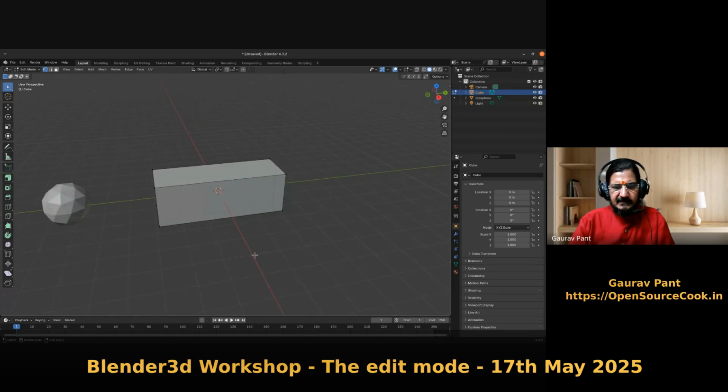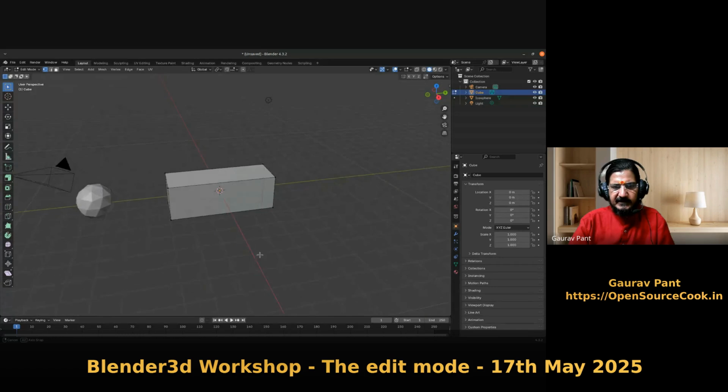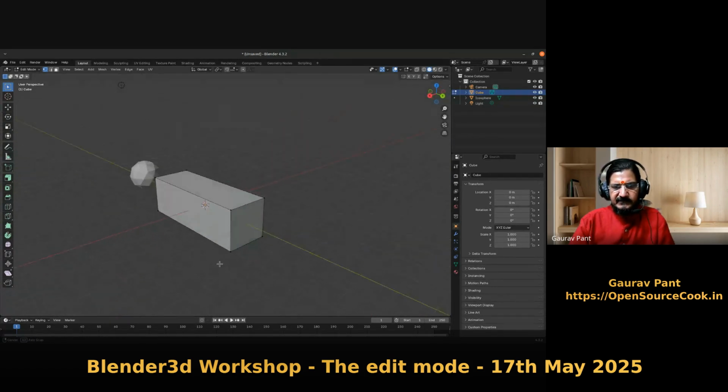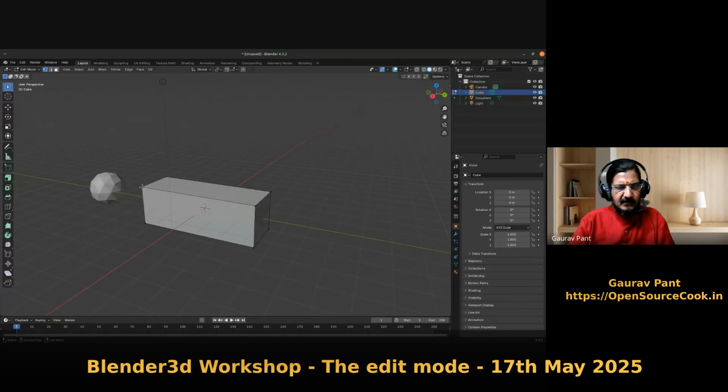So now here, when we are in our edit mode, we can edit this particular object. So editing of the object, as we discussed, can be done on either the vertices, the edges, or the faces. Fine. Now vertices, as you know, do not have any kind of dimensions, so you cannot do the scale operation on the vertices. You cannot scale a single vertex, or rotate a single vertex. They don't have a dimension. Fine. Rotation, scale, and other things are directly possible only on edges or faces.